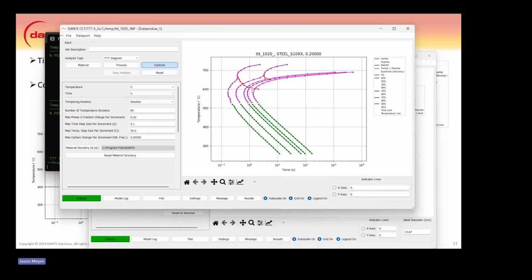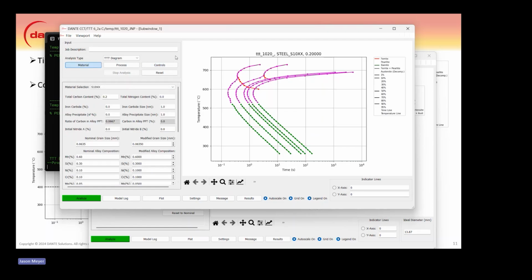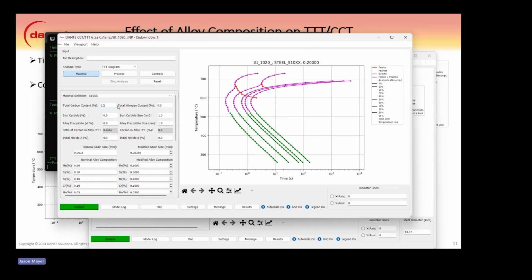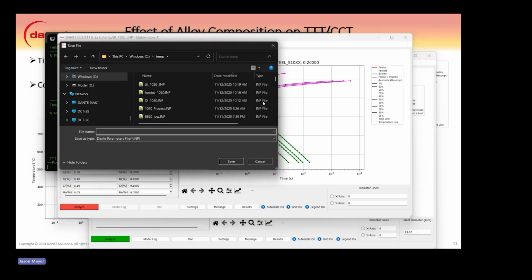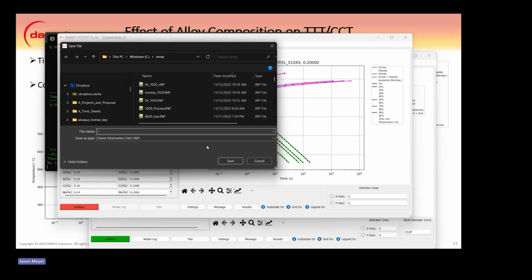We see a little bit of the ferrite range up here, the noses, and then more of the pearlite ranges here. And then we see the bainite transformations here. So if we were to cool down to 400, you can see we have the same kind of data here. We would expect to start around 1 second and to finish around 20 or 30 seconds or so. So we can see the effects of the different hardenability things. So we can choose, again, 0.323 carbon. We can analyze that.